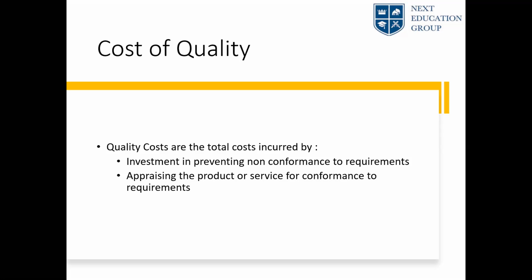Maybe employing a quality assurance engineer, budgeting for audits. Okay, good. So now with regard to building a house, what you would do is, before you do piling, you would take a soil sample and you would send it to your structural engineer to understand the characteristics of that soil, to understand how deep you need to pile. That is an activity you do to ensure quality of the end product.